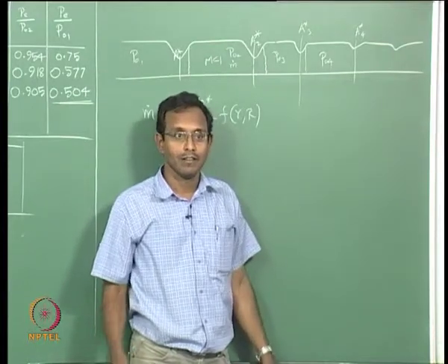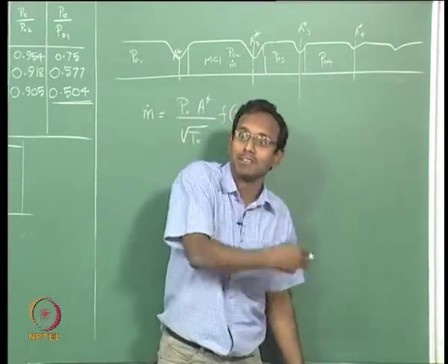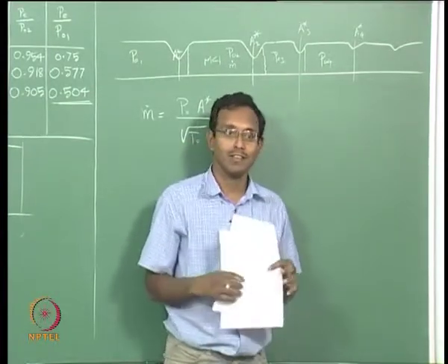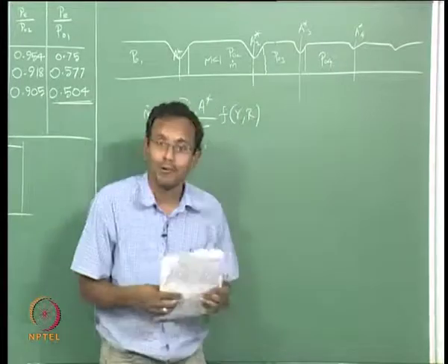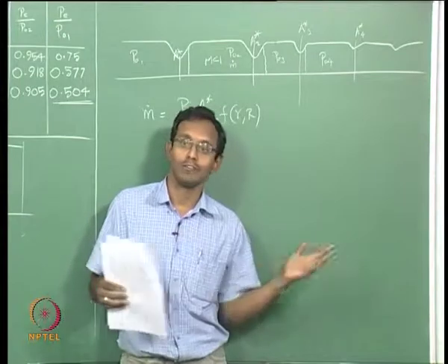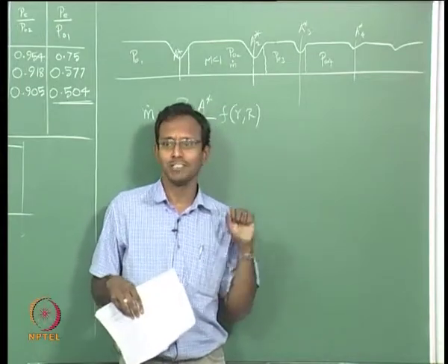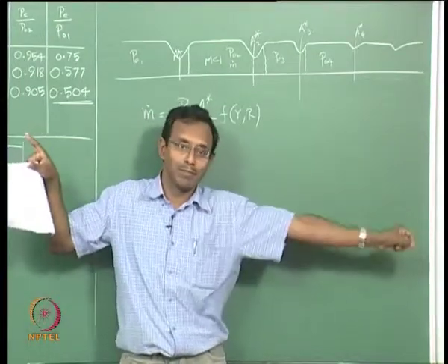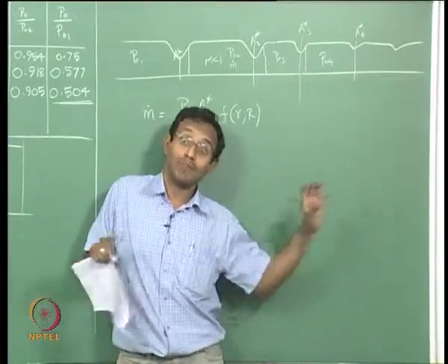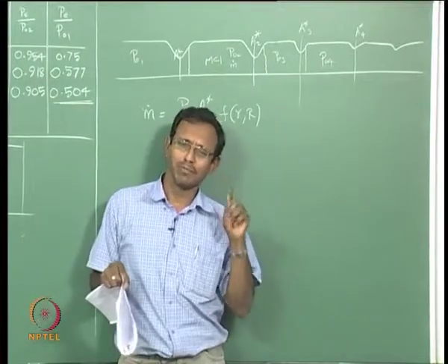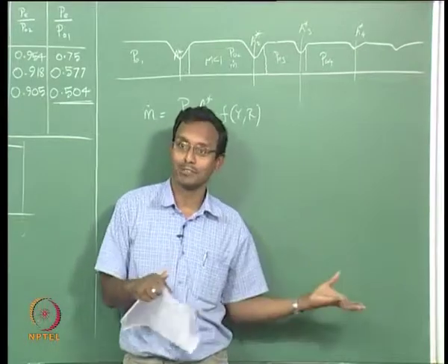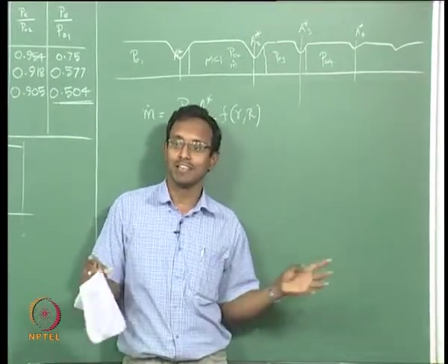Okay. Now that is the statement I repeated 3 times now. As long as PB is low enough. Okay. So now I will go and answer my own question. I said how many times can you choke a duct, flow through a duct. One situation is for a particular P naught and P back, flow is fully subsonic, only some points it is sonic, then it can be any number of times. But if you make any small mistake, only one of them will be there. It is very unstable. Typically it is impossible to achieve in practical situations. So we will think about the other case where there is a shock.